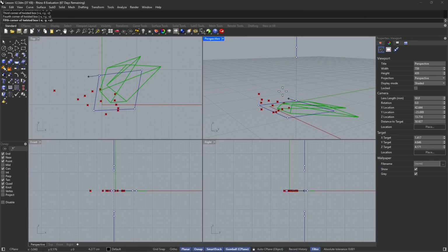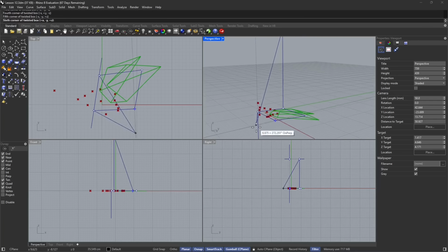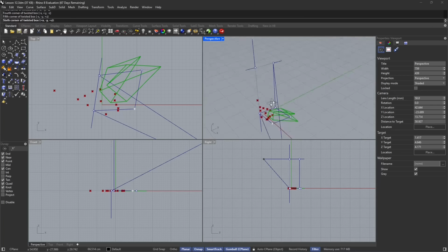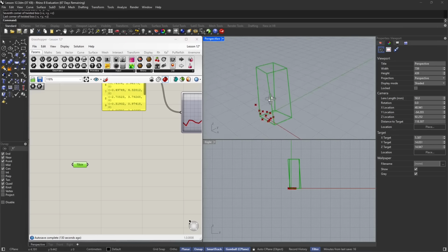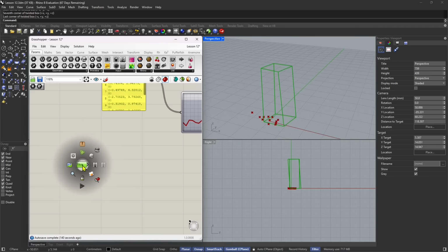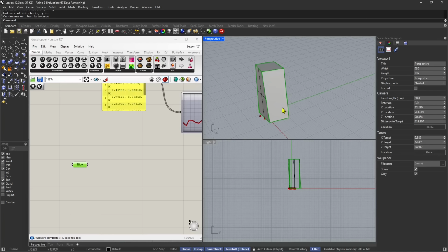3 dimensions. So I'm gonna set the base of the twisted box, and then I'm gonna move up, make sure that my other 4 points are in the top, and you can see it's getting like a planar on that part. So it's positioning those points, and you can see it's a slightly twisted box, and that's another shape. If we bake this, we can see it properly in Rhino as a solid.